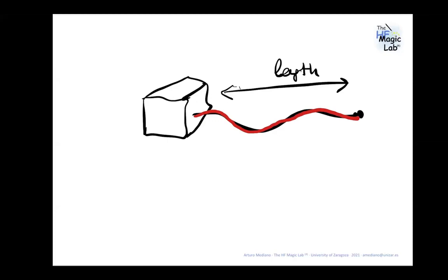If you do something like this, you take your red wire, and the red wire is separated from the black wire by some millimeters, you will radiate in differential mode. So the first idea is to put one exactly close to the other.